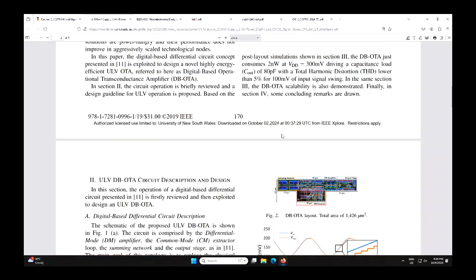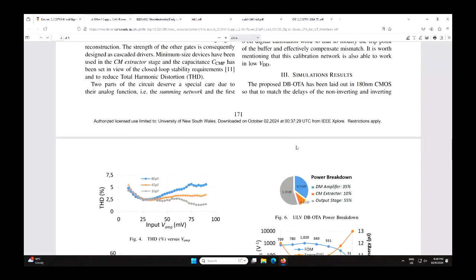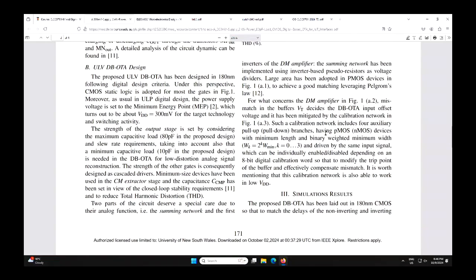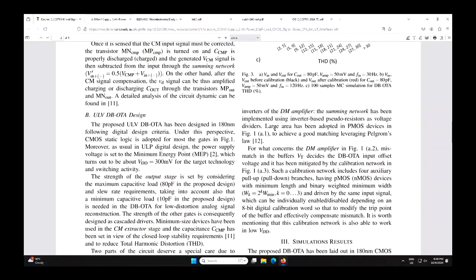I think he mentioned here why we need a larger PMOS. The only thing I can explain is the mu-Cox is different, and to match these two devices it needs a larger area of PMOS. Yes, matching is Pelgrom's law, which we did in the course earlier.